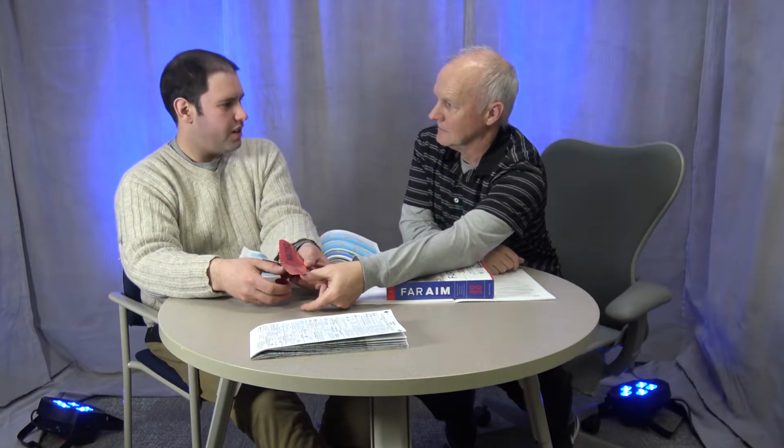So those layers of air, or pressure levels of air, get squeezed in a way between the wing and the ground, and you get higher pressure under the wing. Your flow over the top of the wing, your low pressure, is the same, but as you get close to the ground, that high pressure below the wing actually increases. Right, because it's getting compressed. Exactly.